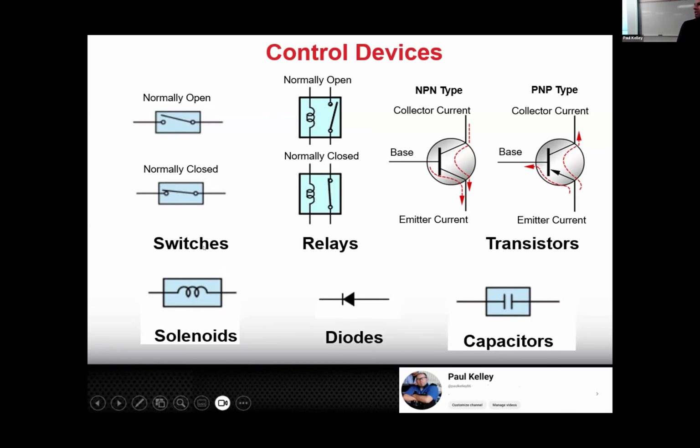So now that's where I jump down here. What a solenoid does, when we send 12 volts through a solenoid and we have ground on the other side, it makes a magnetic field, and that's why there's these little loops. These are the windings. So if we send current through here, it magnetizes the solenoid. Now, I mentioned that in the introduction. The visual one is like the door locks, right? If you energize the solenoid, it goes thunk and it locks the doors. And then if you reverse the polarity, there's different ways to do it, that solenoid can actually open or close or lock or unlock.